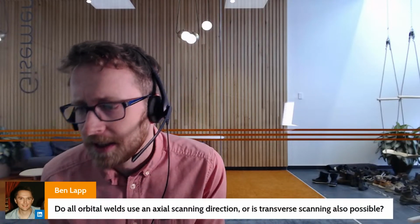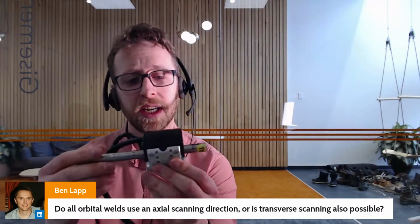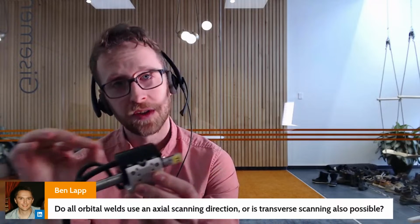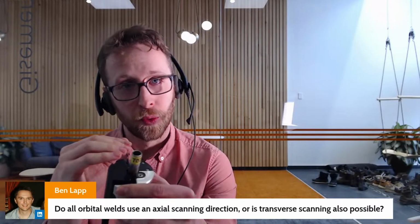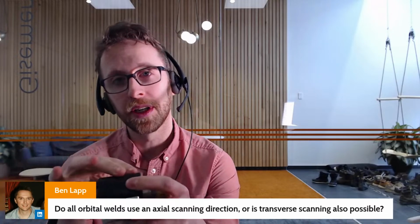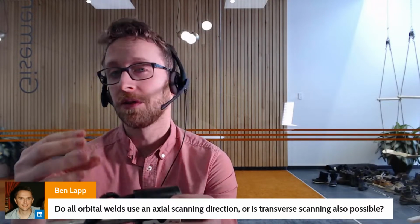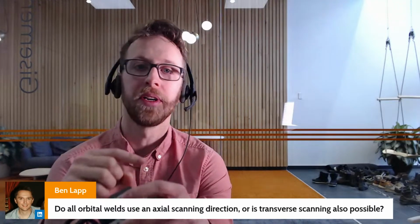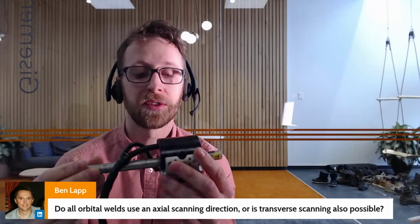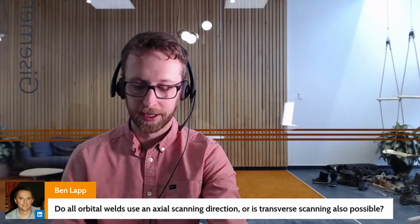Do all orbitals use an actual scanning direction? So it is possible to use a transverse scanning, but those probes were not designed to have a transverse scanning. The scan is done actually. The main reason for that is if you're trying to do a transverse scan on an orbital weld, the weld will alter a little bit the electromagnetic properties of the material. And when you're nulling the probe, you're nulling all channels on different part of the weld. And so you're having a much better signal to noise ratio when scanning actually than when doing transverse. We did some tests. We could design a probe that does it transversely, but you get a much better signal to noise ratio doing an actual scan. So this is why we use it like that.